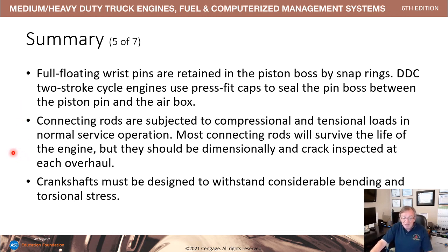Connecting rods have both compressional and tensional loads on them, so we're going to have to pay attention and examine the connecting rods thoroughly for cracks. That we're going to do with magnetic particle. Cranks are designed to withstand the constant bending and torsional stresses.